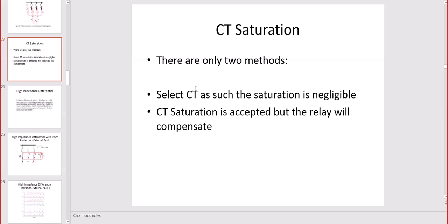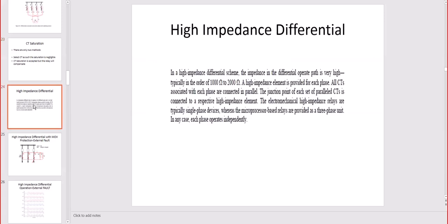So that is translated in the standard as a 5P10. So the CT will accept 5% plus or minus. The error is not a problem for the protection, because the protection doesn't need to be very precise. It is a range where we want to trip in order to protect the system and avoid the damage curve.